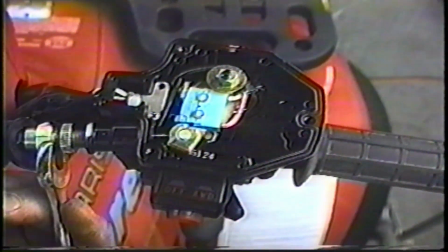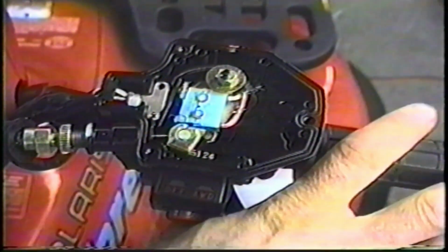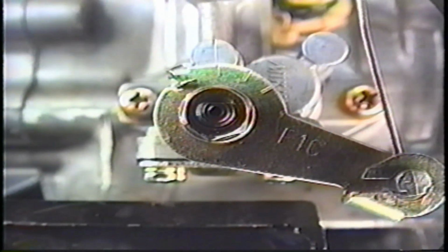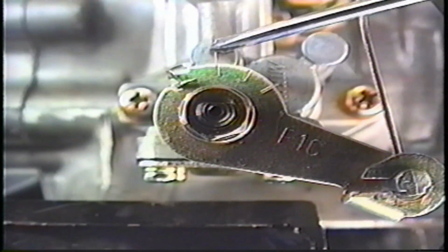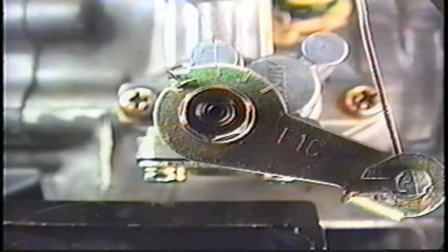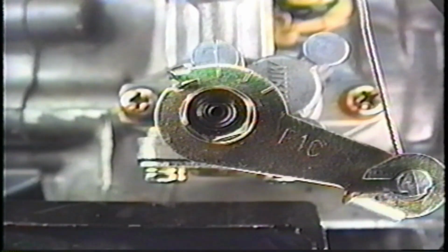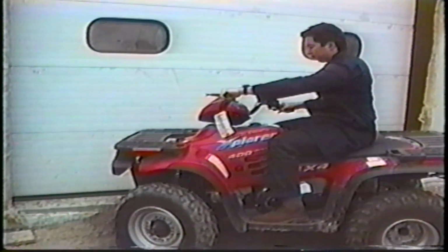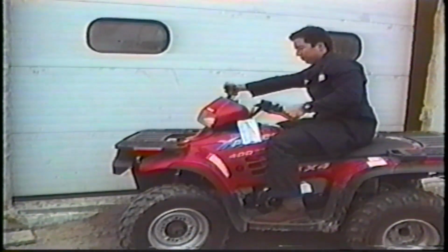Throttle cable adjustments affect the oil pump on 2-stroke engines. Be sure to check oil pump adjustment after setting the ETC switch. Once everything is properly adjusted, start the engine and turn the handlebars full right and full left to see if the RPM increases. If it does, recheck ETC switch adjustment and routing of the throttle cable and wire harness to find the cause of the problem.